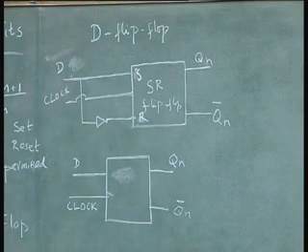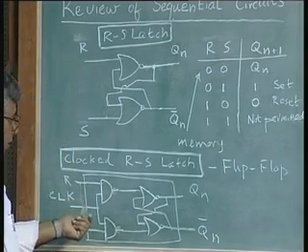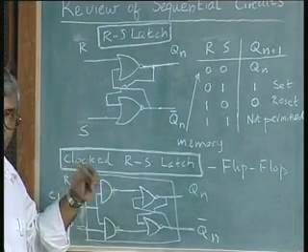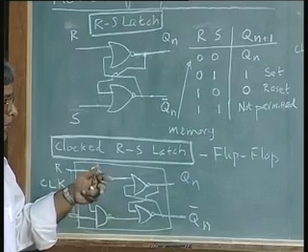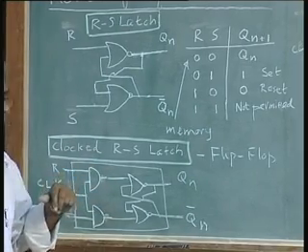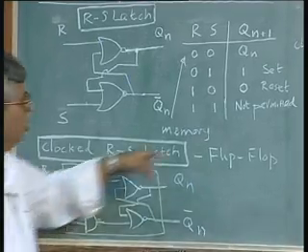What we would have got earlier with an inverter on the simple RS flip flop would have been a D bar flip flop. We do not want a D bar flip flop, normally it is not used. That is why I said it is not a mistake, it is a convention. In textbooks you will find D flip flops, not D bar flip flops. That is why I thought I will change it myself and call this S and R.